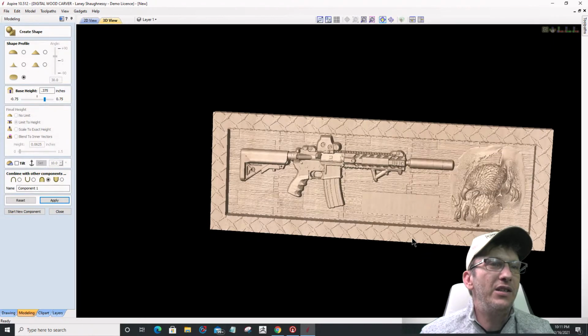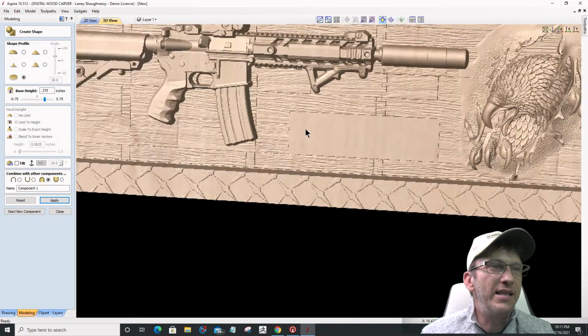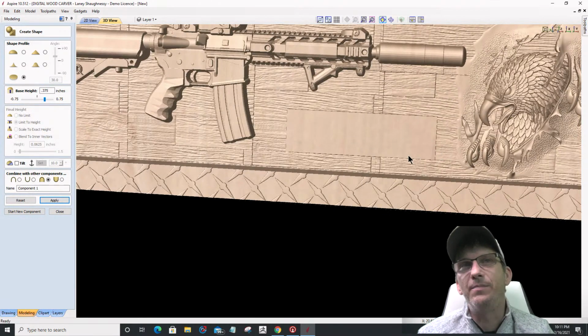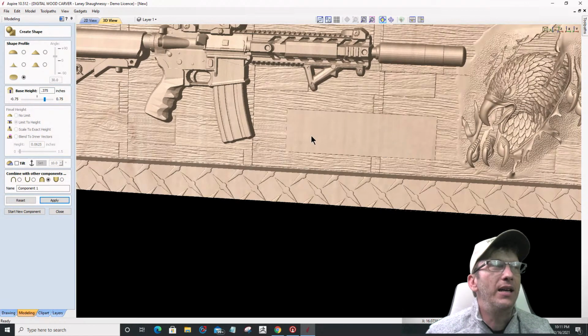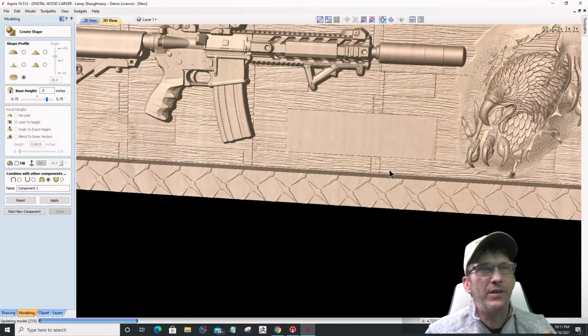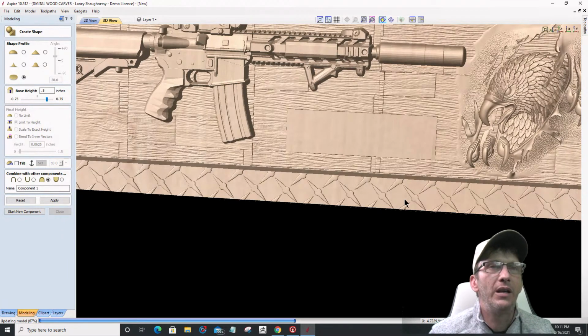And that just gives me basically a place to put someone's name or whatever, right? So let's go a 1/2 inch up, 0.5, click apply, give it just a little bit of a lip and all that.